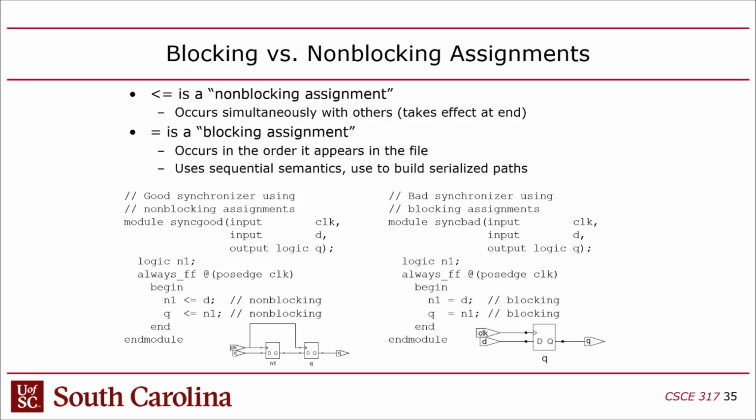And by the way, I generally don't do combinational logic in an always, unless it's a special case, like a really big if-then-else, like in the control unit in 611. I usually use an assign for combinational logic. I only use always for sequential logic. You guys with me? In other words, I only use the always for memory. I mean, well, I shouldn't say that because that is actually clock logic the way it's written there. But I don't write code with an always that implements non-memory if I can avoid it.